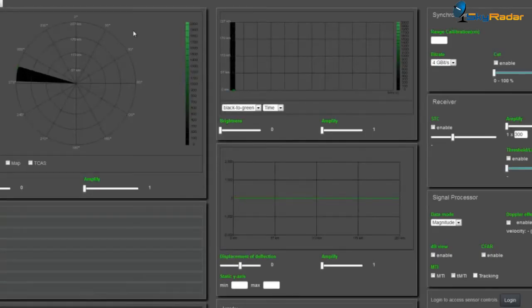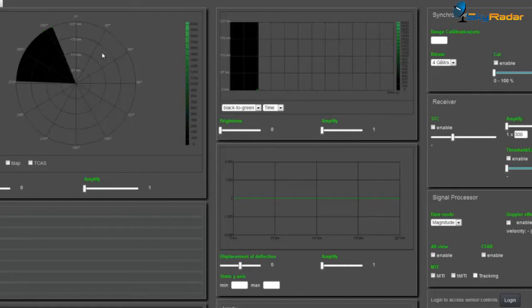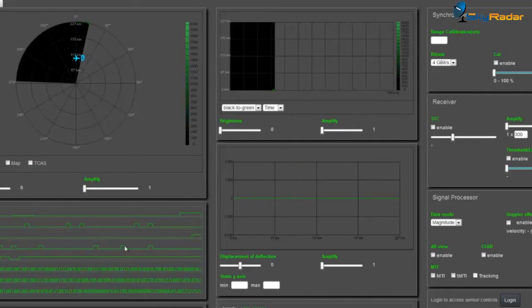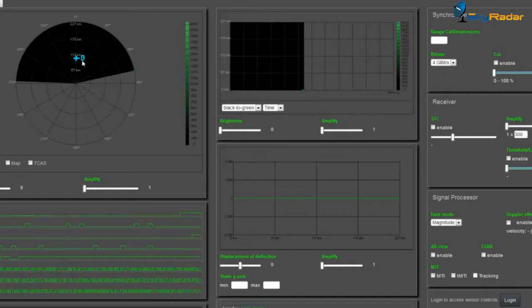Let's now look at the secondary surveillance radar. We have the PPI scope, and in the PPI scope we get signals of aircraft. It's a collaborative scenario. We only get the signals when we get signals actively sent from the transponders of the aircraft. You will see here now the first case, two overlapping aircraft. We always display the data of the second tracked aircraft. You see that overlapping, so we see two aircraft very close. You'll see later on, once we switch the alert mode on, that the controllers get an automatic system alert in such cases. But let's look at the system itself.